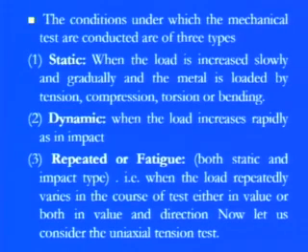The second type, as per its name, is dynamic, when the load increases rapidly, because in dynamic loading the force is absolutely dependent on time. When dynamic forces are there, just like when a shaft is moving, or gears are rotating, or a camshaft is moving, impact loading is always coming. Impact means a high amplitude of load coming, just boom like that, and then releasing.